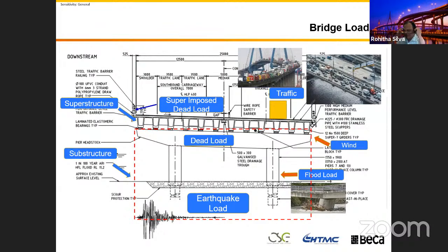When I went through the British standard and the Eurocode, the expected design life of the bridge for these standards is 120 years. I think 120 years is stretched a further 20 years. You need to have a significant QA, QC process to achieve that. With my experience, especially in Australia over the last 14 years, to achieve 100 years is really a massive challenge, but if you extend to 120 years, it's a lot.